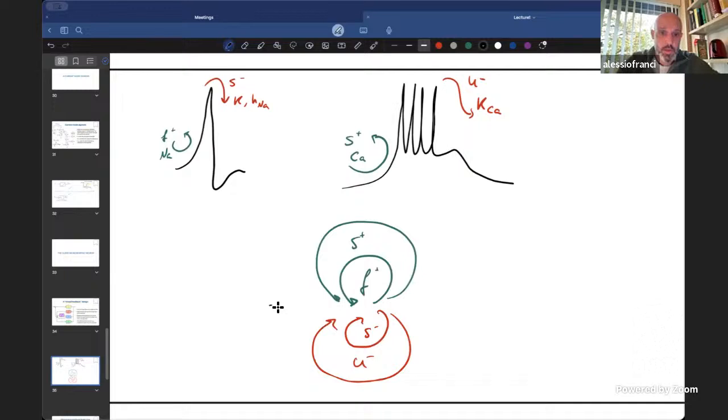Entering here, you have the input current, and in a neuron you have the membrane potential at the output of your circuit. Because we are working with current mode circuits, instead of a voltage we have a membrane current instead of a membrane potential. Everything is about current in our design. We have no voltages, essentially, or voltages are hidden, but it doesn't matter.